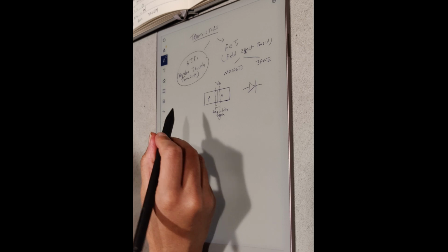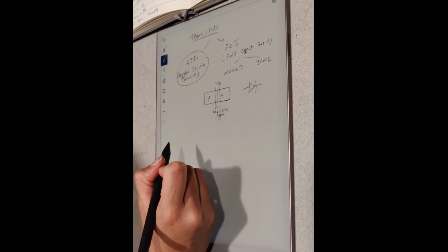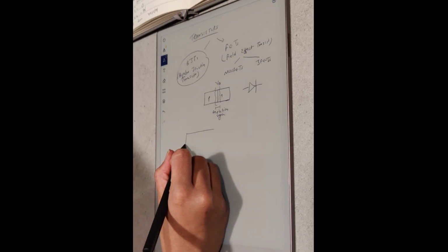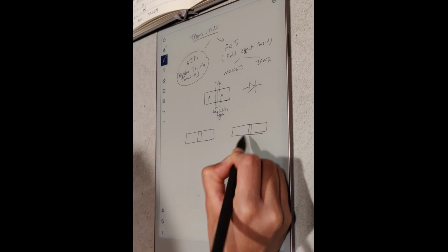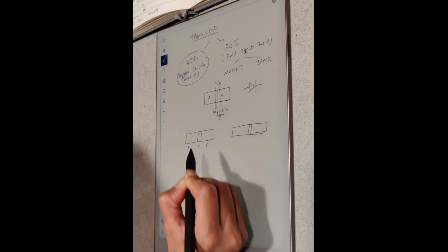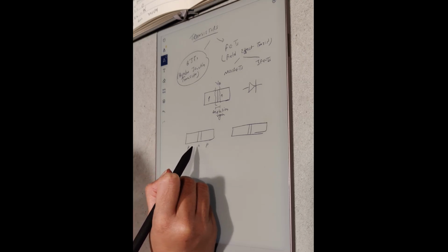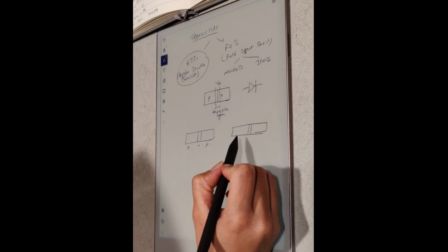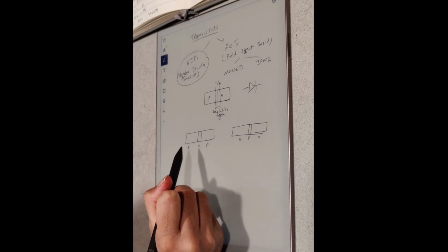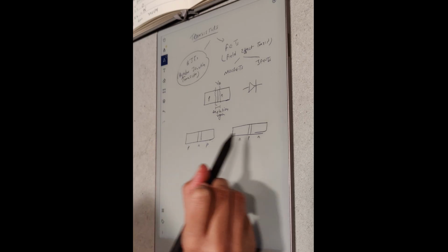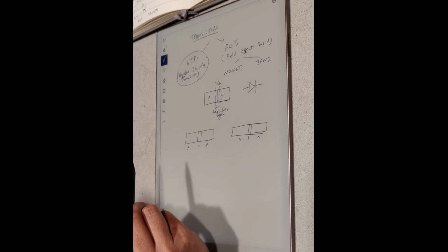Now let's talk about transistors. So transistors are a three-terminal device as opposed to a diode, which had only two terminals. Transistors, we can have two kinds. So we can have a transistor called PNP, which means you have a P-type semiconductor on both sides, and it has N-type semiconductor that is sandwiched between the two. Or you can also have NPN. The important thing to remember is that the middle region here, whether it is N or P, has to be very thin and lightly doped.